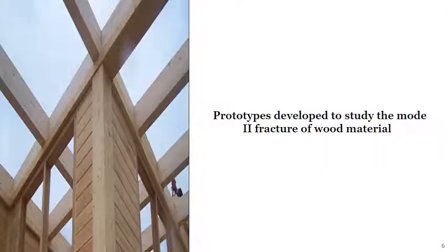In order to understand and control the phenomena related to this mode of rupture, several prototypes have been developed, mainly ENF, ELS and 4ENF, but others have been designed and applied. Indeed, the Mode 2 stress intensity factor (KIIC) for balsa wood was measured by Wu using thin plates with a central crack, taking care to use specimens long enough to test the hypothesis of an infinite plate model.